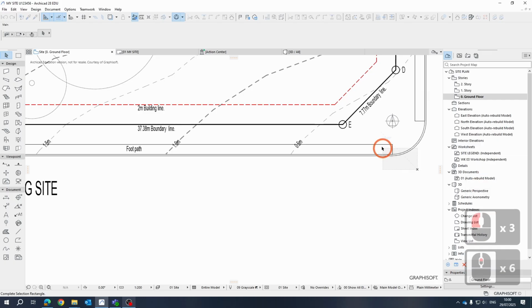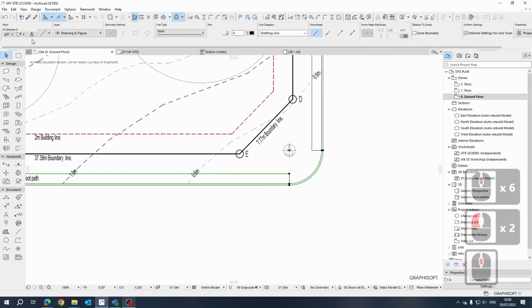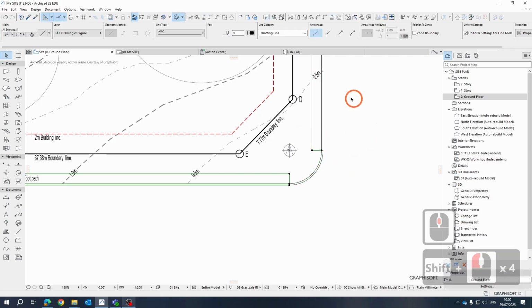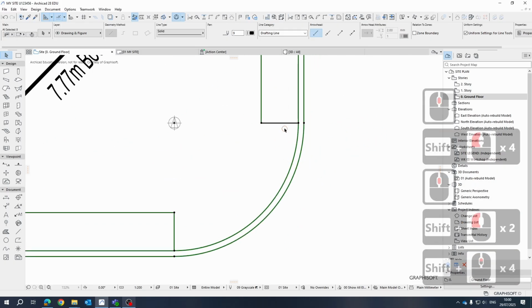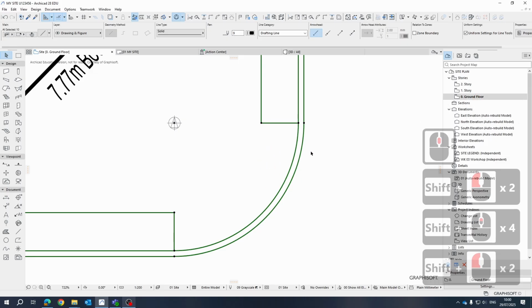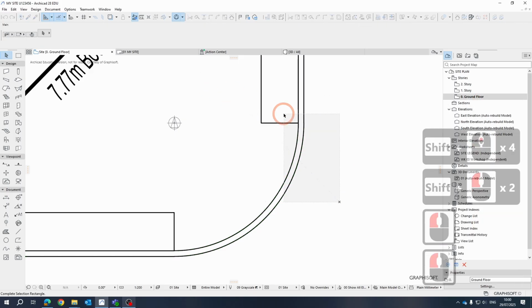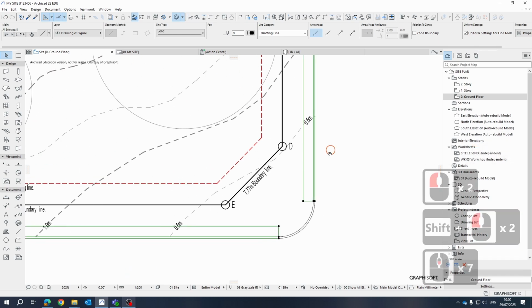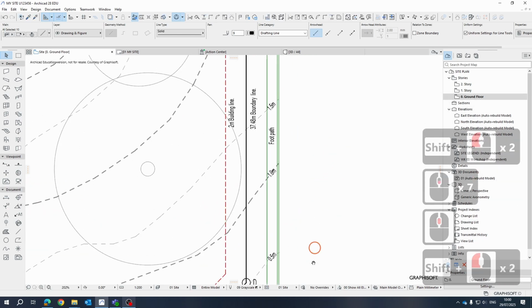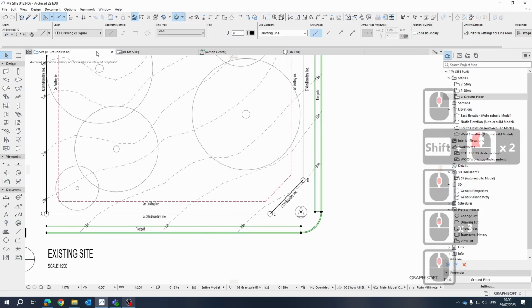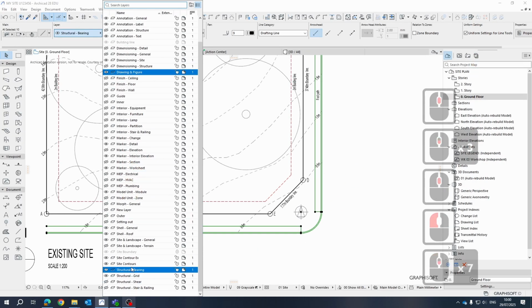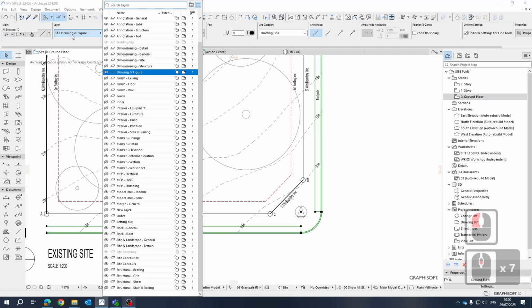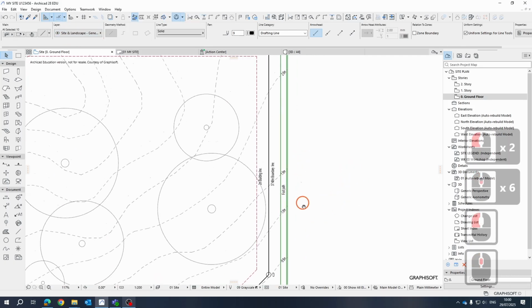This line work, I'm going to select all of this line work. So remember, use the cross selection tool at any point. So hold shift down to select more line work. I'm just going to put all of this line work. Yeah, I've just noticed if you hold shift down. Okay, now just make sure that all of this line work gets put on to the correct layer and path as well. So make sure that goes on to site drafting. So site general, because it's drafting, it's your site information.